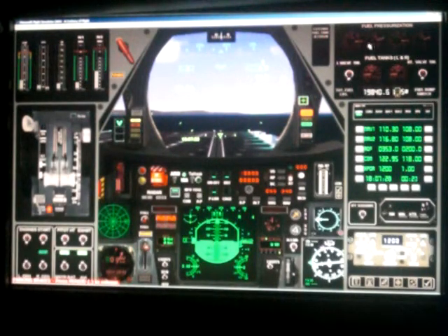While we're here, you can see the fuel tanks and fuel pressurization gauge. It's got a left and right fuel valve switch and a fuel bleed and dump switch, and then your comms and radios are located here, followed by your DME 1 and 2 and an IFF squawk that you can turn on if you'd like. And on the other side, you'll see the engine indication gauges, the parking brake switch, a pushback switch, the throttle, and then your engine start switches, your left generator, right generator, pitot heat, an exhaust smoke system switch, your master avionics, and your master battery. And so that's basically the sidearms panel.